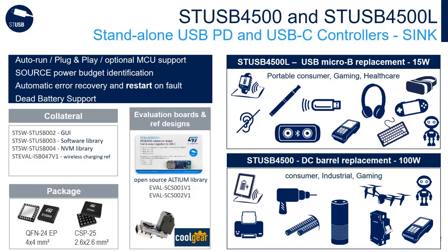Although the NVRAM on the ST USB 4500 includes default PDO programming, it can be customized to support any application with only basic know-how about the standard and limited software skills. No need to be an expert at all thanks to the NVRAM programming GUI that ST provides. In addition, we provide example design materials, including schematic, BOM, and open source Altium libraries for layout.